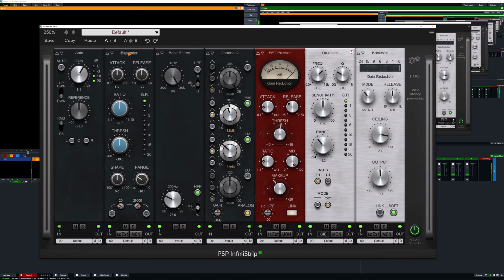Now, there are other fancier noise reduction systems, FFT-based systems. You take a profile of the noise. Those, again, they can introduce quite a bit of latency. And sometimes these Space Monkey artifacts, which I don't find that I get with just standard expanders or even noise gates. Next up, simple high-pass filter just to take out any rumble, reduce the bass a little bit, and control any kind of plosives that might be getting through the windscreen. It's doing a pretty good job.